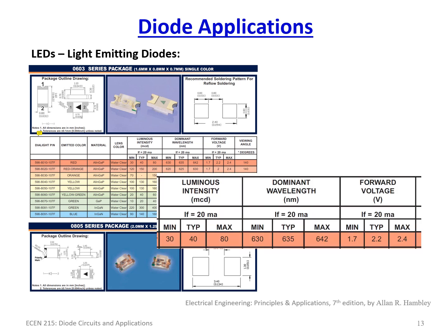So here's just a zoomed in view again, particularly looking at, in this case, red, 2.2 volts. Maximum, if you're designing something, you usually use the max voltage, so you make sure that you have sufficient voltage to guarantee forward bias. And again, this is actually VD. So this is the forward bias voltage, where mostly for the signal diodes we were looking at it was about 0.6, 0.7 volts. This is now 2.4 volts. And you want to have, for maximum intensity, about 20 milliamps.